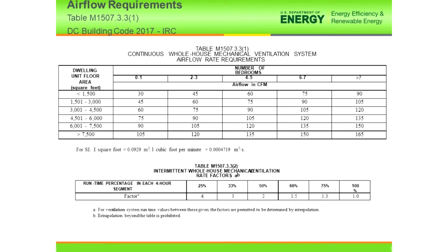Now, there's something called indoor air quality that we are really concerned with when we get down to these air changes below 5. And right now, the 2017 code says that your air changes shall be 3, 3 air changes per hour. That means you're going to have a whole lot of stagnant air inside your home. This indoor air pollution can really affect children and older folks with respiratory problems. You're going to have to find some means of venting this air, exchanging this air. The inside of the house can be just as dangerous as the air on the outside.